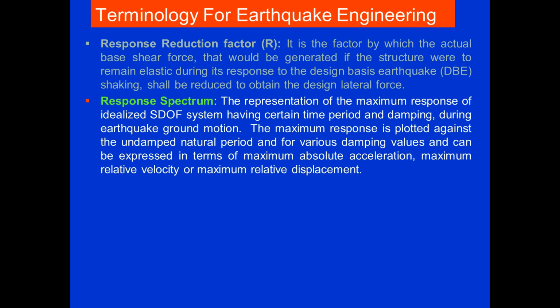Or you can simply define this terminology as a plot between the natural time period on the x-axis and the absolute acceleration on the y-axis. Based on that, whatever peak acceleration you get during an earthquake is recorded as a response spectrum.